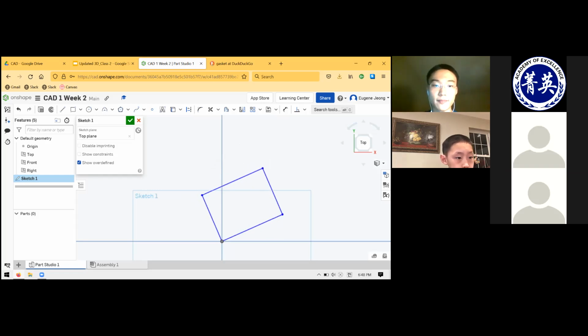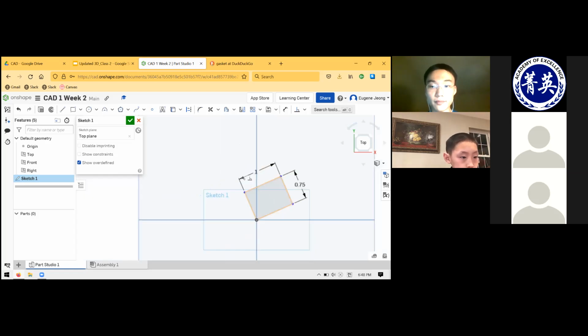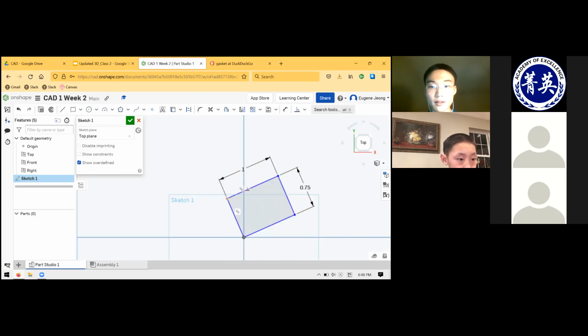How do you delete the dimensions? So dimensions, it's very similar to any other sketch entity. In fact, almost every entity you can delete first by selecting it to bring it into focus. You can left click on it. So I know that I'm selecting this dimension here because it's highlighted in orange. And then I can just hit delete on my keyboard, which will get rid of it.